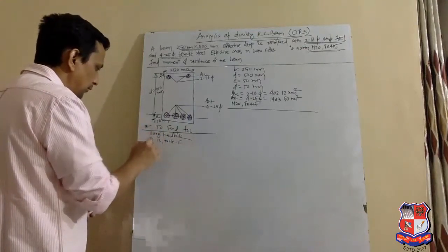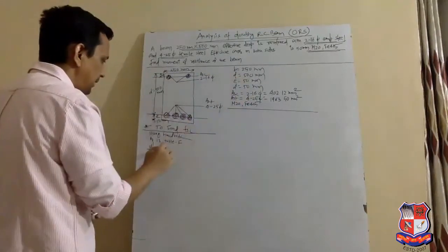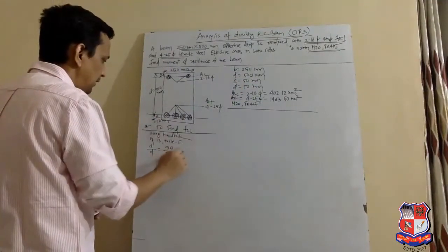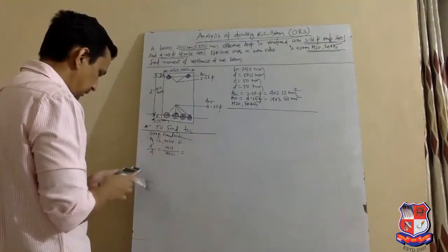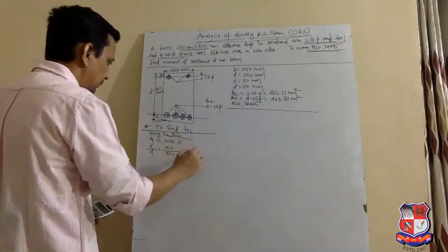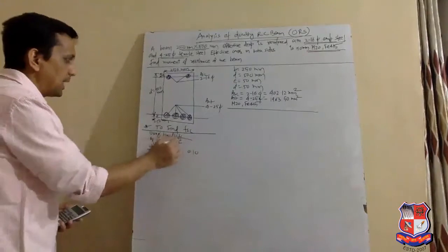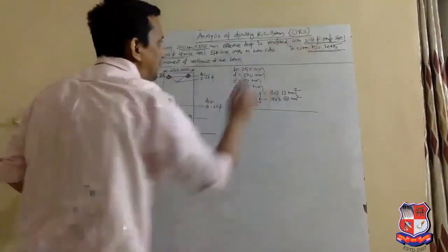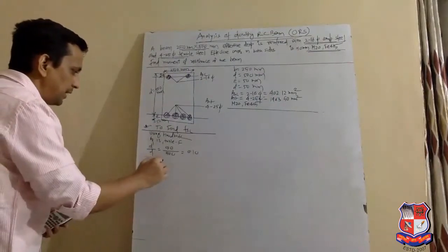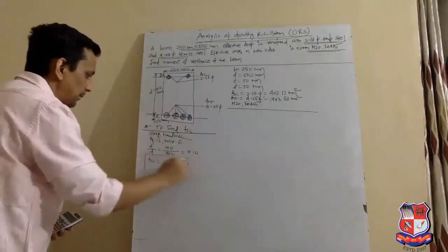For that, we need to find d dash upon d. We have d dash 50 mm and the effective depth is given 500 mm. So 50 divided by 500, we get 0.10. Using d dash by d equal to 0.10 from table F, and for Fe 415 grade steel, we get directly FSC value 353 Newton per mm square.